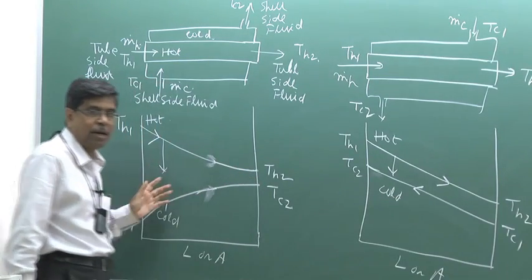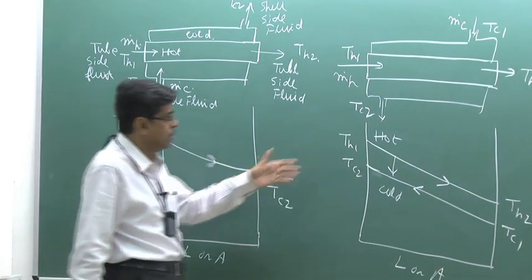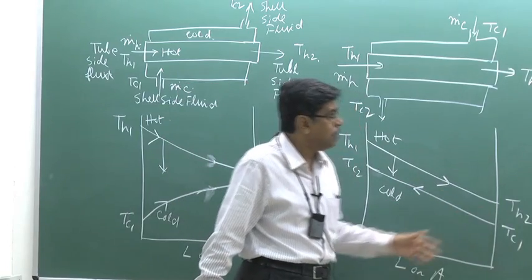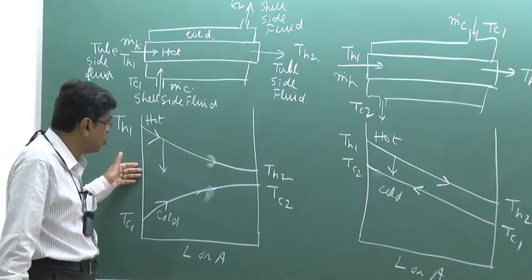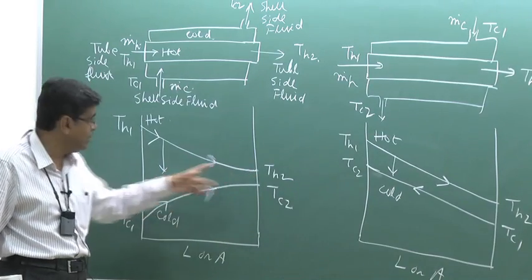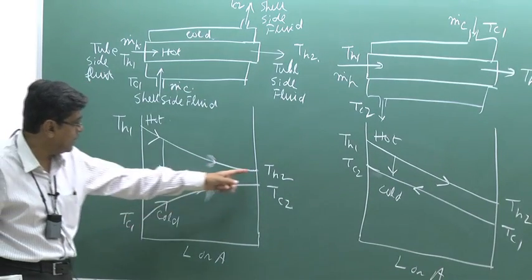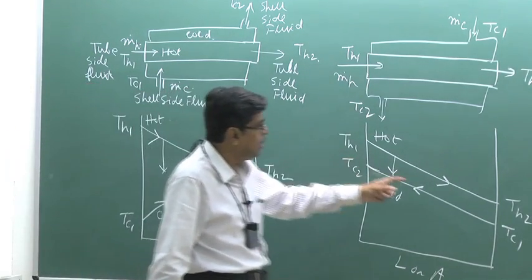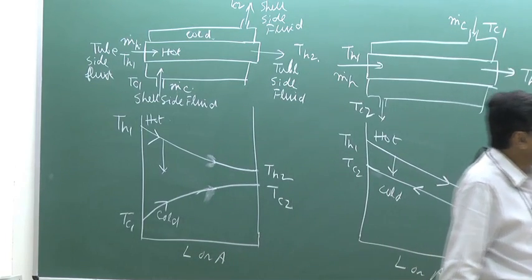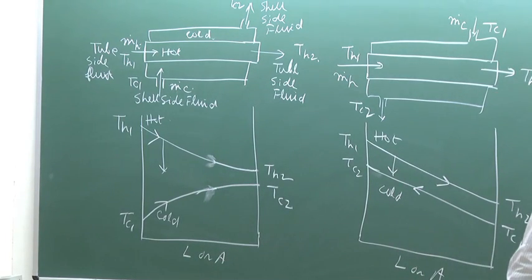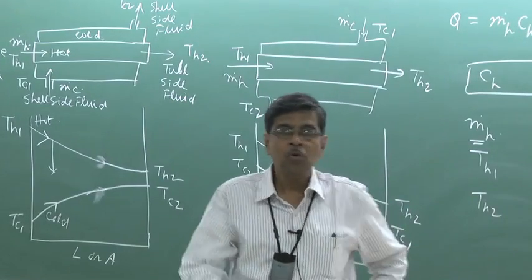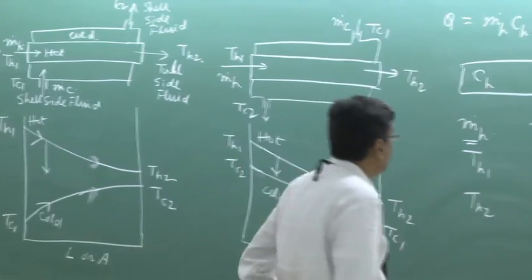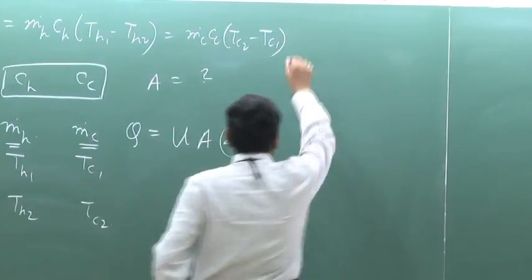Here we have the inlet and outlet, because both fluids are flowing in the same direction. From one section to another, there should be some mean delta T, a mean of these two extreme differences, this one delta T and this other terminal delta T, in such a way that we could define this equation. So to find that delta Tm, we have to do a small mathematical exercise.